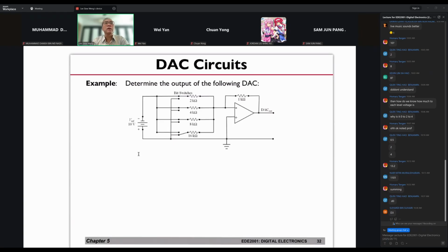So this is what happens here. You guys can see from the diagram, this is 0 volts here. So it will be 0 volts here. Now, can anyone tell me what's the voltage on this side? What's the voltage here? Negative 10. Yeah, someone mentioned negative 10 is correct because this is a battery. The positive connected to ground means the negative part will be 10 volts lower. Very well done on that. So the voltage here is going to be negative 10.